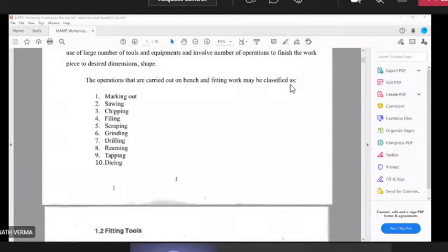So in the dot punch, there is a 60-degree angle. Then center punch, there is a 90-degree angle. Then there is a drift or number punch. In number punch, you can put the numbers and then just punch it so that we can put the number in our material like 1, 2, 3, 4. Then there's a letter punch, also the letters used A to Z and symbol totaling 27 numbers. So number punch is similar to letter punch in construction, but has numbers at its end.